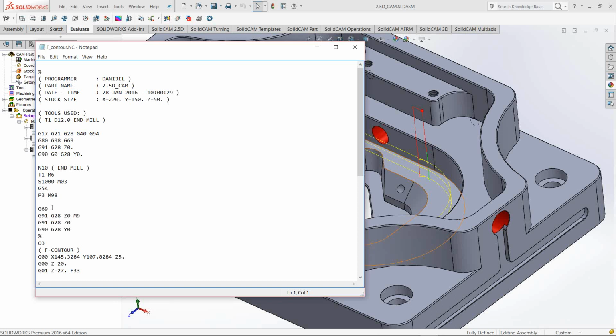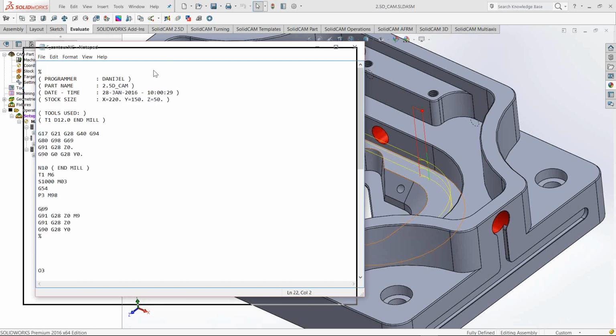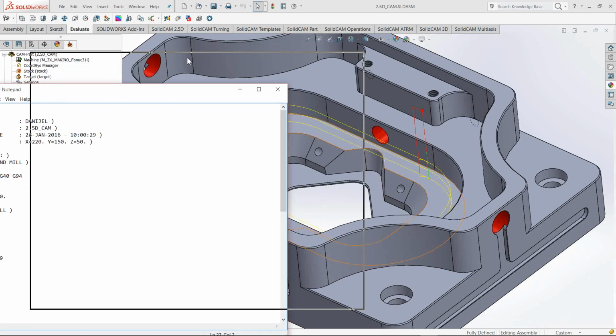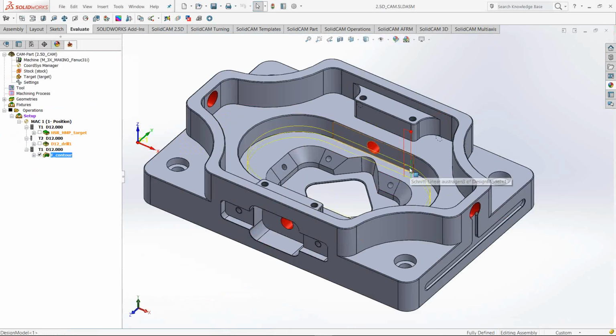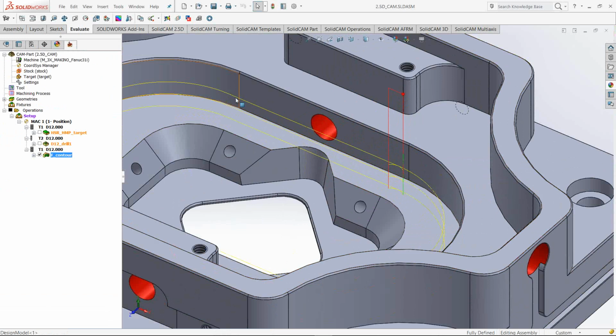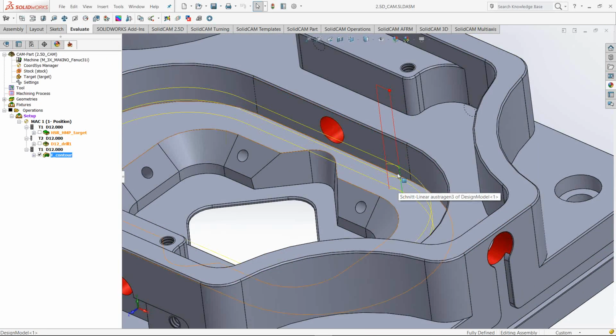Now, here you can pay attention. This is our main program, like we had in the previous example, but the sub procedure will generate the subprograms if you have a repetition of the same toolpath. So here we have one toolpath, then we have the down step, and again repeating the same path.